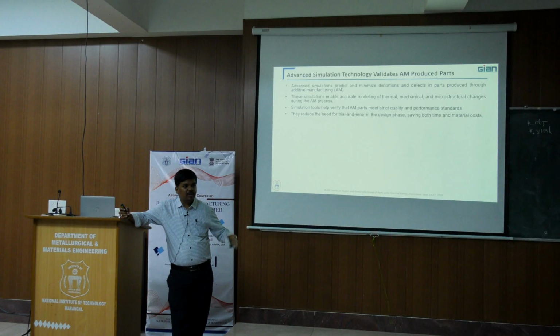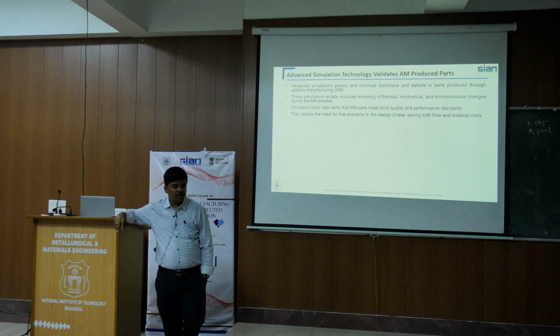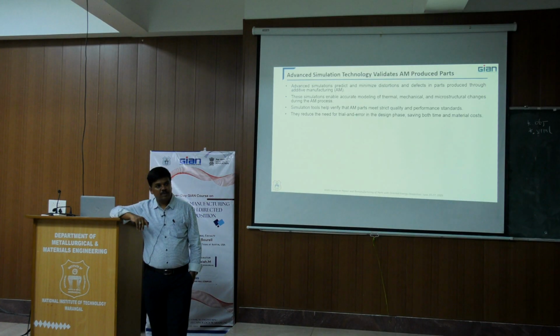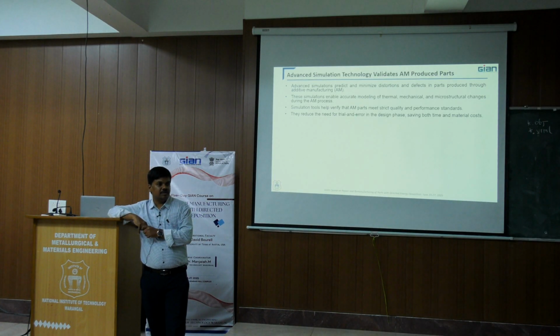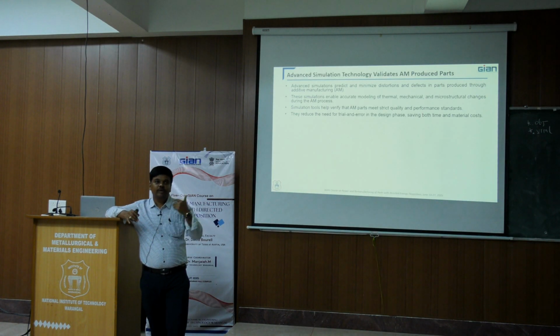or DM3D and others. They will give you standardized optimal process conditions only for a few materials. They might give them for titanium, stainless steel, 17-4 PH, aluminum, or even Inconel, because research has mostly been done on these materials. But if you want to use customized materials, such as bronze or gold or other materials, a lot of the research data needed to feed the optimal process conditions into the machine is not available.